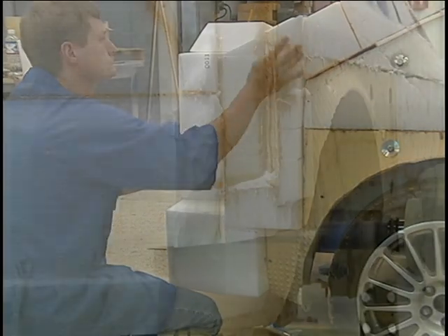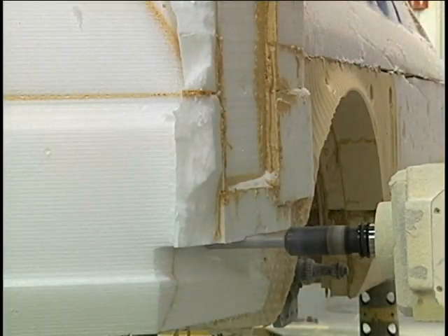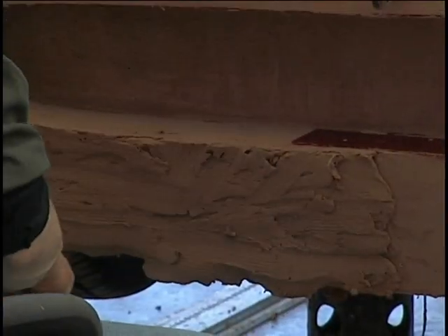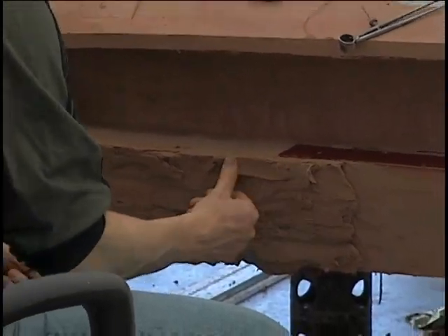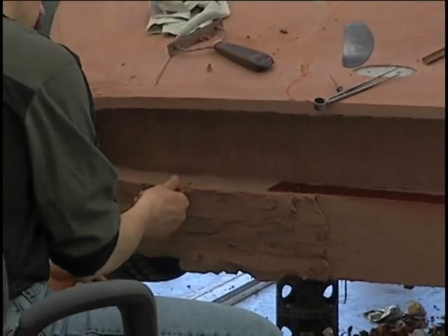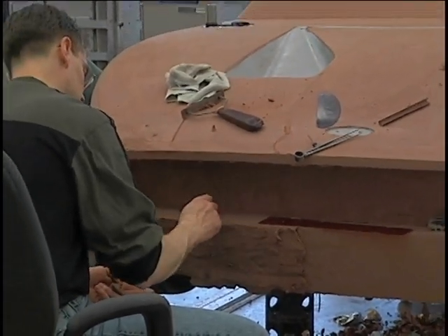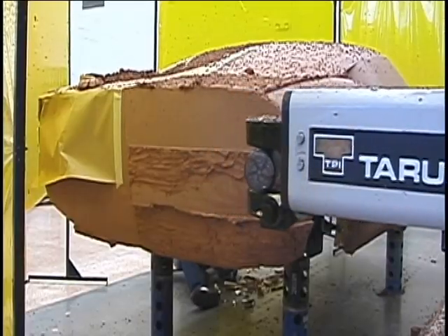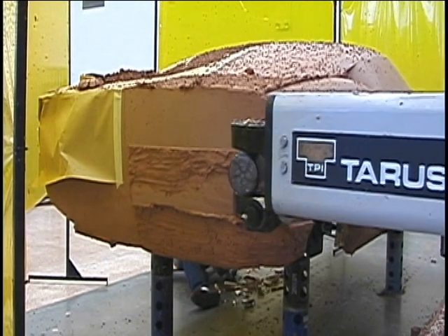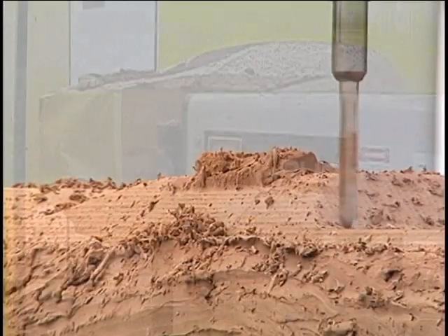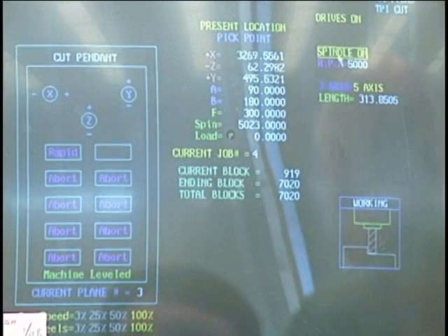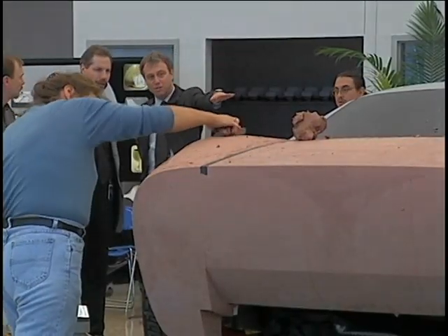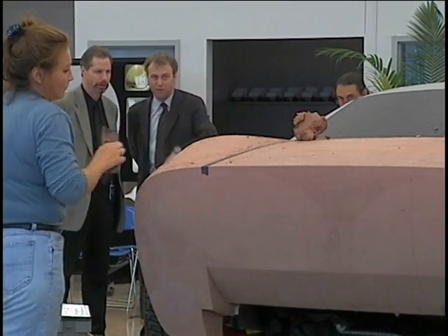The foam is oversized and it must be milled back 2 inches under the scanned surface. Once the foam milling is complete, the armature is delivered to the design studio where modelers apply clay over the foam. The clay must be applied in layers and cooled very slowly. This provides a good, solid, workable surface for the 5-axis torus mill to cut using the selected Alias surfaces from the CAID design process. The full-size model is evaluated after the first milling.